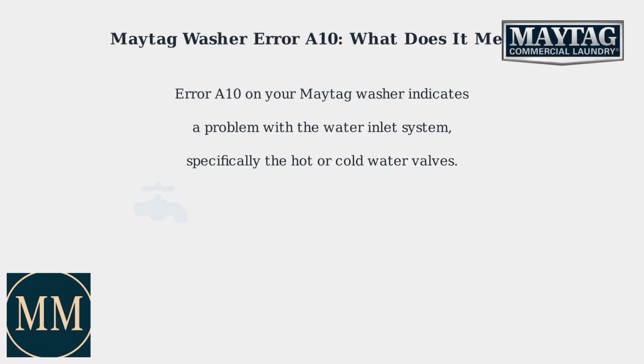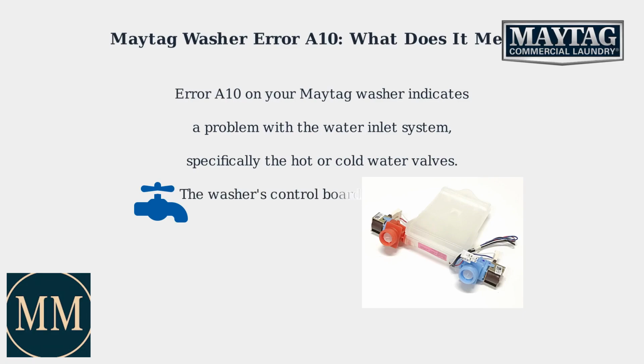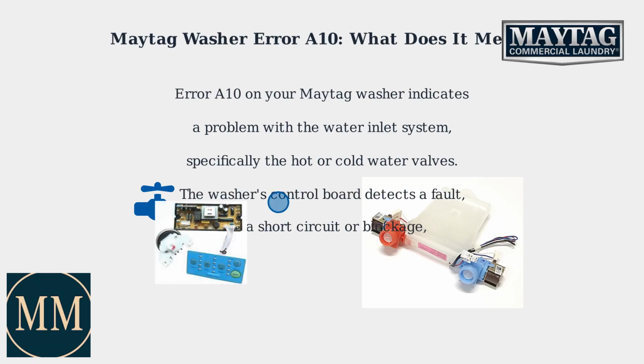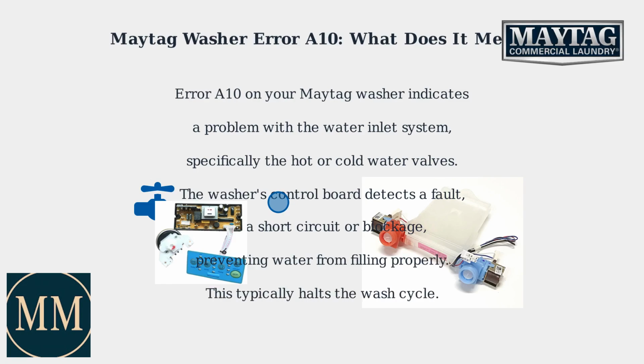Error A10 on your Maytag washer indicates a problem with the water inlet system, specifically the hot or cold water valves. The washer's control board detects a fault, like a short circuit or blockage, preventing water from filling properly. This typically halts the wash cycle.